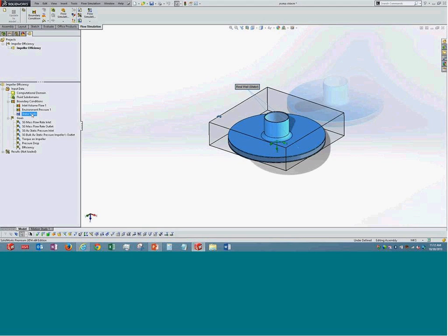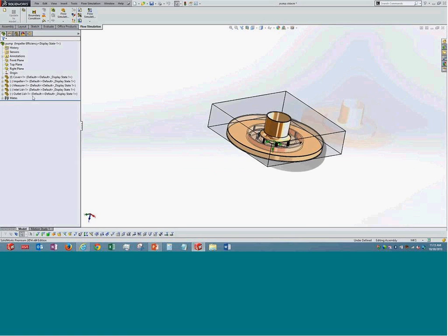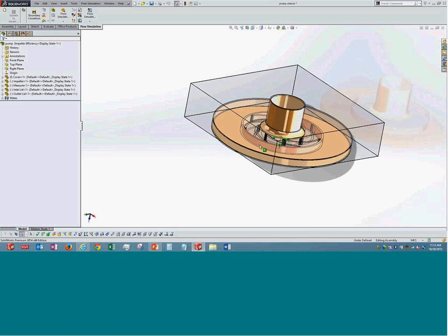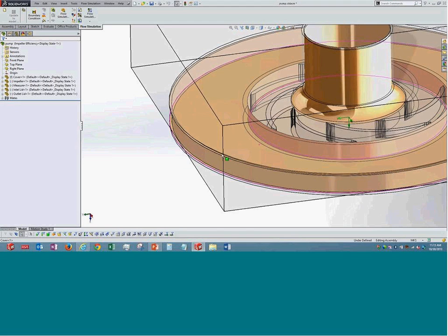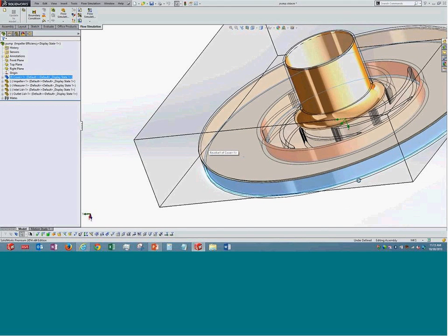We select all those surfaces which are not going to rotate and tell the software that they are stator. The ones which are not specified as stator are assumed to be rotating and will be taken into effect using the global rotating region option. Now, typically, other goals will come into the picture, such as specifying mass flow rate at the inlet and outlet, and average static pressure.